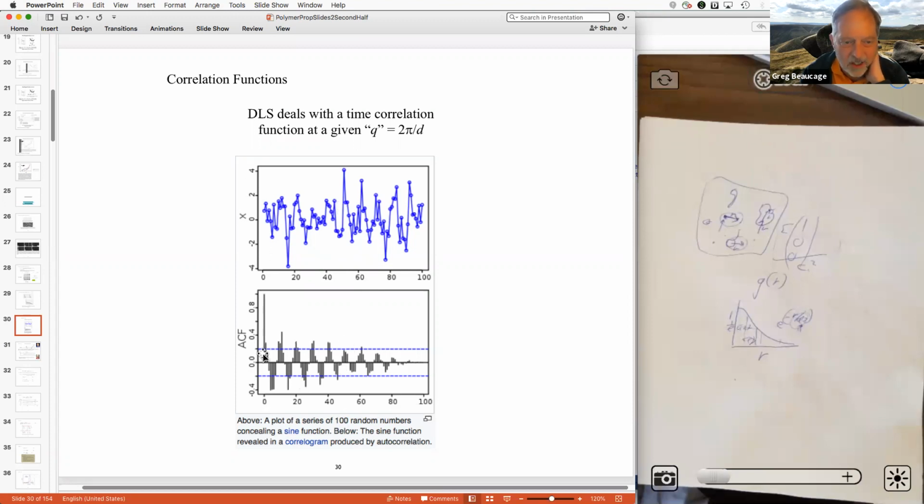So you're finding, say, if there's a bunch of sine waves in this data, then you come out with sine waves here. Right? Any data can be represented by sine waves. So the relationship between this noise pattern and the amplitude pattern versus frequency is the Fourier transform. It's going to try to fit sine waves to this. The amplitude of the sine waves versus their frequency is going to be this pattern. So this noise pattern can be decomposed into a series of sine waves with these frequencies, these amplitudes. That's the idea of this.